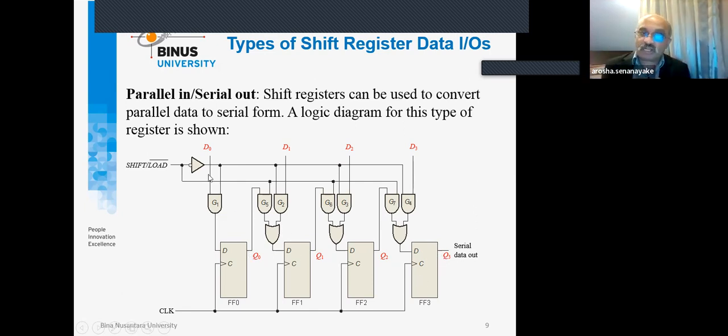In order to construct that type of circuit, as you can see, you need combinatorial circuits, for example in this case an AND gate. We have two AND gates and an OR in this case, so that this output should go through these to get as D. Depending on the shifting that occurs, you can see that it is connected to this. What is the meaning of that? Therefore we have two important signals. What are they? Shift and load.